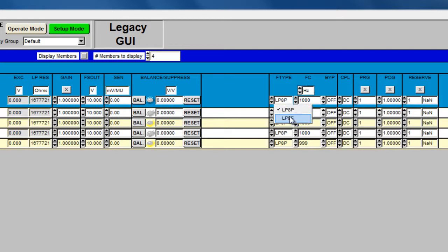The pulse mode filter, similar to a Bessel response, provides a linear phase characteristic that is useful for time domain measurements. The flat filter mode, which is similar to a Butterworth filter, offers a flat passband and sharp attenuation slope and is useful for frequency domain applications. Each channel offers independent control of the programmable filter's corner frequency and filter characteristic mode.